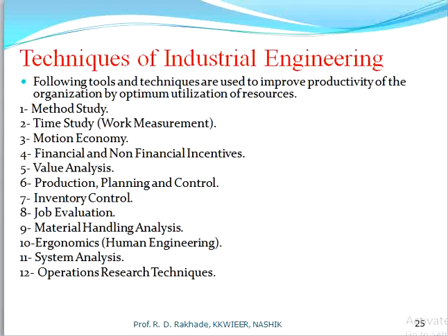Method study basically works to improve the existing method to minimize cycle time. Second, time study, that is work measurement to evaluate the standard time of a qualified worker. A qualified worker means a worker who produces a product with quality, with quantity, and by considering all safety measures. So standard time is evaluated for an average worker, considering all allowances.